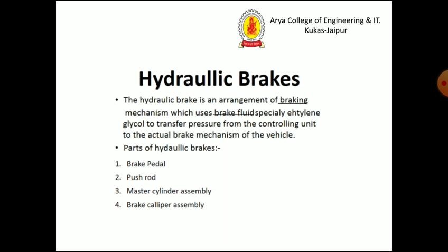Hydraulic brakes. The hydraulic brake is an arrangement of braking mechanism which uses brake fluid, especially ethylene glycol, to transfer pressure from the controlling unit to the actual brake mechanism of the vehicle. The basic parts of hydraulic brakes are brake pads, push rod, master cylinder assembly, and brake caliper assembly.